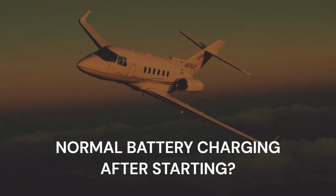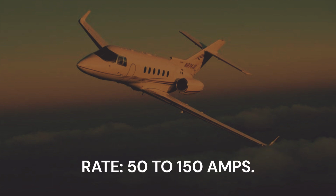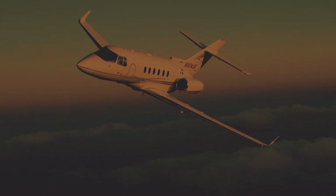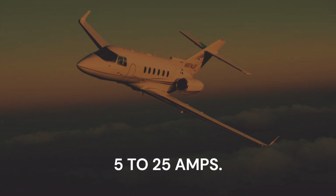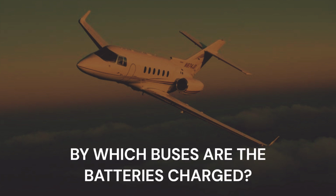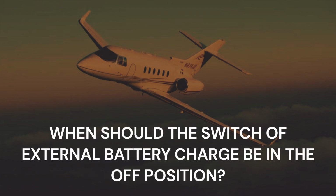Normal battery charging after starting. Rate, 50 to 150 amps. Rate of battery charging with external power. 5 to 25 amps. By which buses are the batteries charged? PS1 and PS2. When should the switch of external battery charge be in the off position?